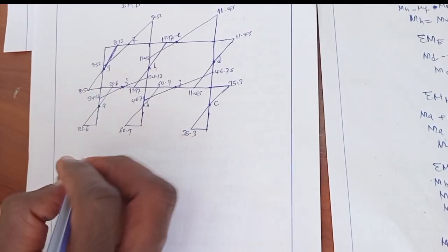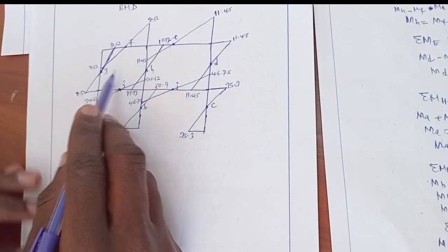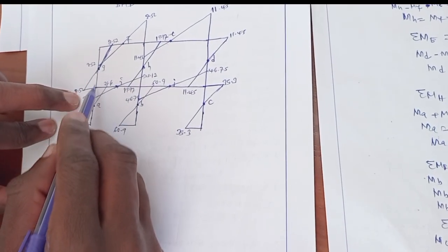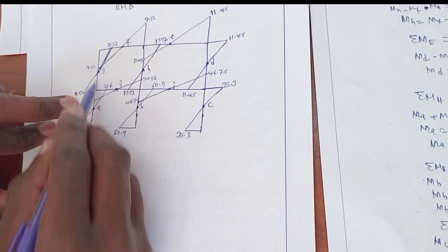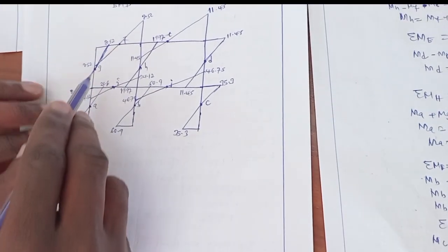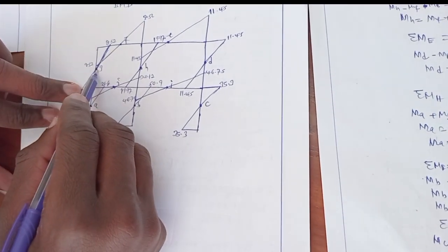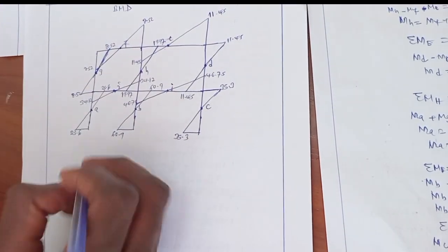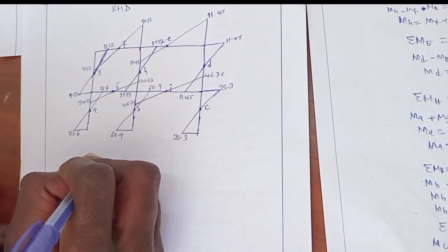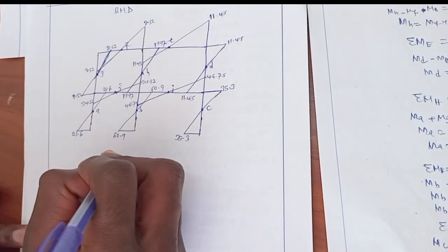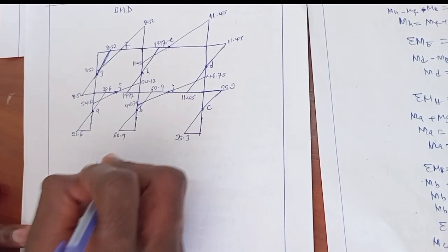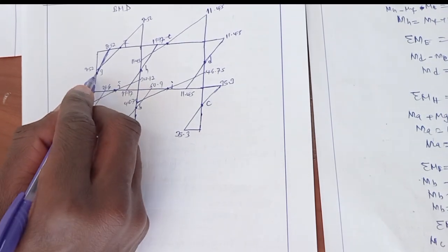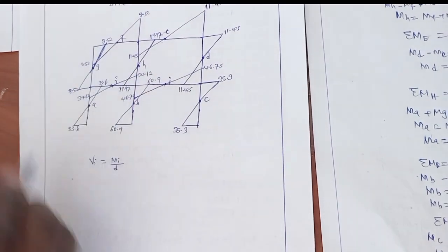The shear force of vertical members is obtained by taking the bending moment of vertical members divided by the distance from the point of inflection to the ridge joint.